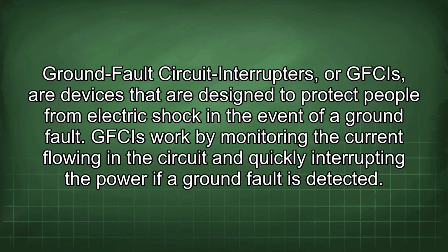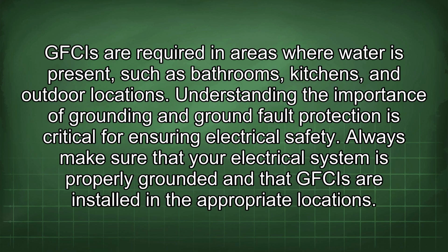Ground fault circuit interrupters, or GFCIs, are devices that are designed to protect people from electric shock in the event of a ground fault. GFCIs work by monitoring the current flowing in the circuit and quickly interrupting the power if a ground fault is detected. GFCIs are required in areas where water is present, such as bathrooms, kitchens, and outdoor locations.